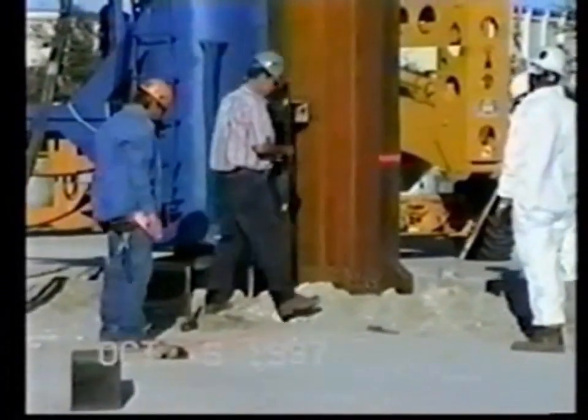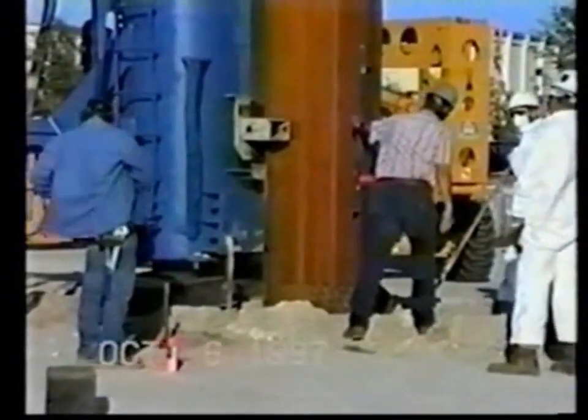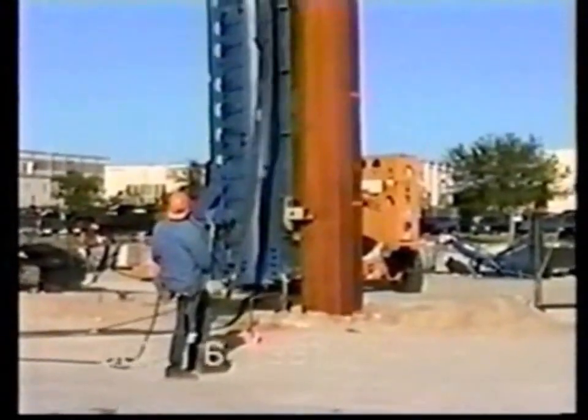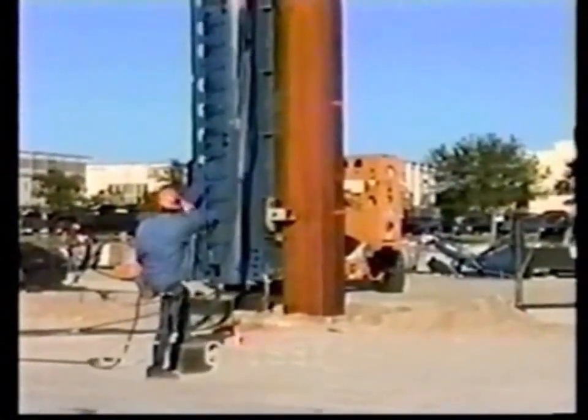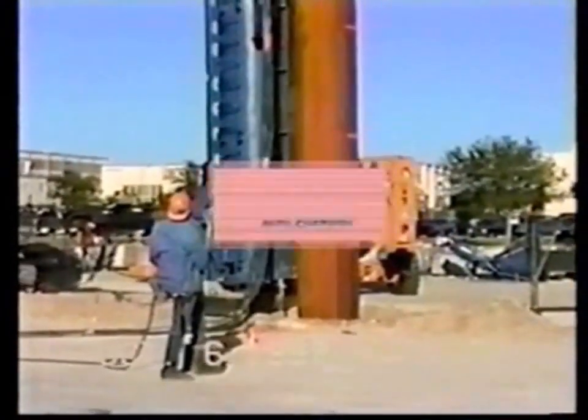Once into position, the plumb is checked one last time with a 4-foot carpenter's level. Finally, the beam is vibrated into position using a 22-ton electric vibratory hammer. Each probe took between 6 and 10 minutes to drive under optimum conditions.